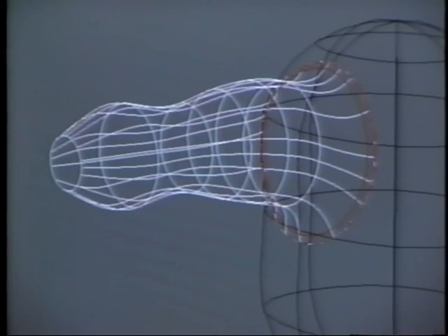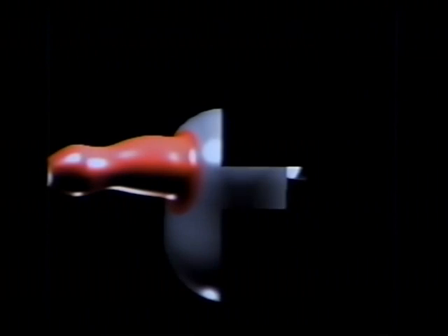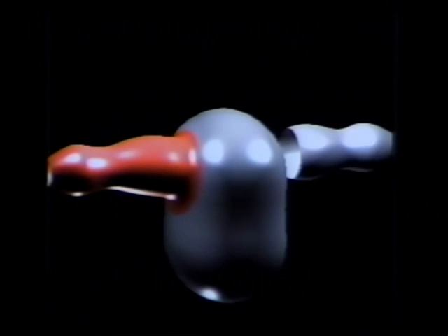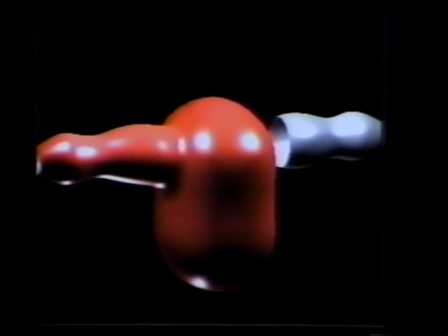Now in texture mode, we can scale the texture down to only fit around the base of our arm. Notice the gradient it makes between the arm and the body. Now, if we match the color of the body and the arm, then with this map an imperfect fit in the shaded view can render completely seamlessly. And this brings us to the next section of the tape, which will focus on rendering.